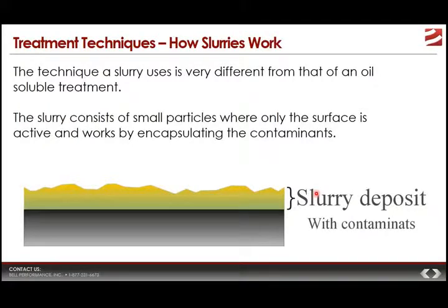I mean, MgO is about as simple a chemical compound to manufacture as there is out in the world. They take that and they mix it into some kind of liquid and they create a slurry, kind of like when you're cooking and you create a flour slurry for thickening things. So they make a slurry out of magnesium oxide in some kind of carrier, and they deliver that into the fuel oil by injecting it, and it delivers the magnesium that way.